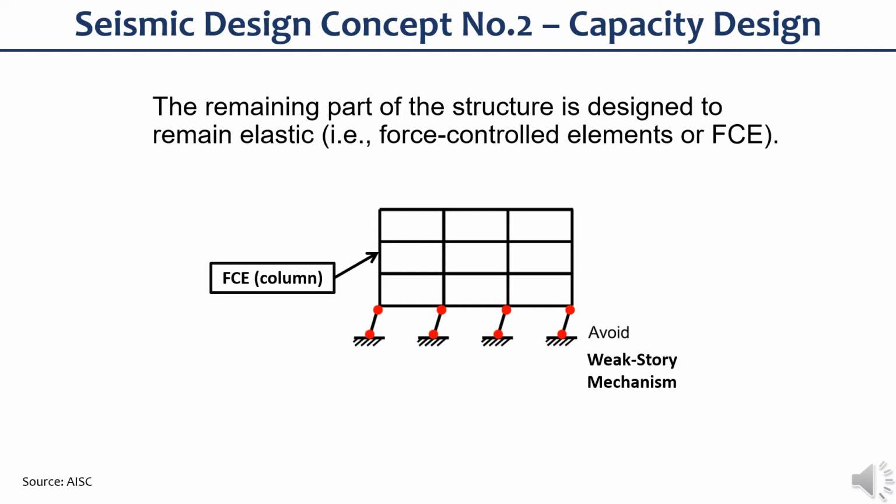Now, capacity design is an approach used to design structures for seismic resistance, in which the strength of the members comprising the seismic load resisting system are proportioned such that inelastic behavior is accommodated in specific designated locations that are adequately detailed to accommodate this behavior. When these elements yield, they limit the force that can be transmitted to other elements, effectively shielding them from overstress and allowing them to resist design earthquake excitation while they remain elastic. This practice permits the elements that are not expected to yield or experience inelastic behavior to be designed and specified without difficult detailing practices intended to provide for ductile behavior.